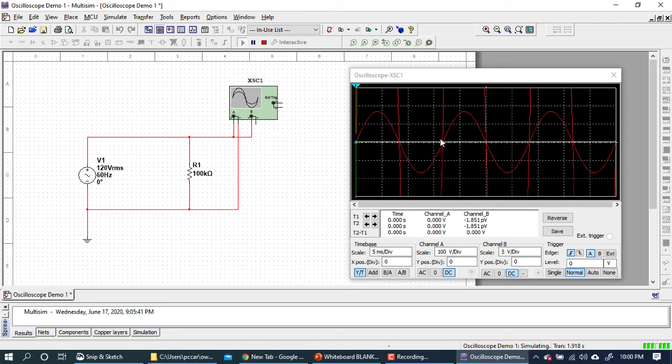Now you can see there's 2 waveforms on the screen, and I'm going to adjust. So now it looks like there's only one on the screen, but there's actually 2. One's on top of the other. To get the screen where you can see both of them, you can superimpose waveforms over top of each other if you need to. That works good in some instances.